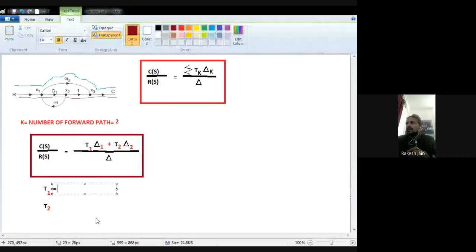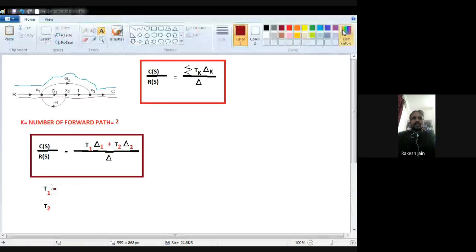Now in the same color I write it down, so you will not be disturbed. Purple color for the first forward path. There is no meaning to the color; I just show you so you will not lose track of the data and the graphical representation. In the question I mark the first forward path with a pencil in purple. Now I have to write down the gains. So what is the rule? Just see the forward path, write down the gains of whatever branches come, and multiply the gains with each other. That will be your answer for the gain of a particular forward path.